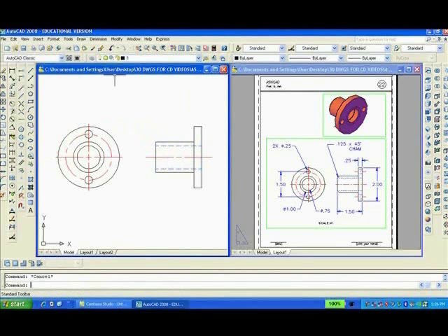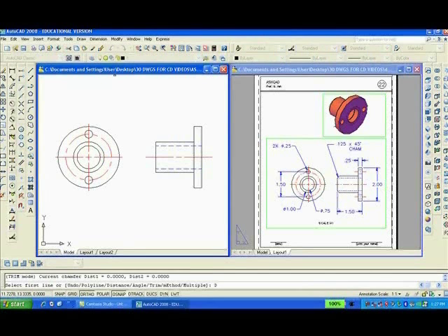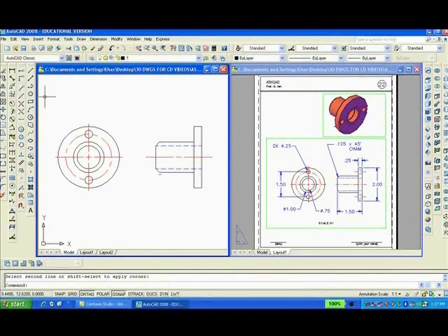So far, so good. Next, you want to type CHA, enter for a chamfer, D for the first distance, 0.125. They ask for a second distance, just hit enter to accept it. And then pick the two lines, here and here, enter. Here and here. And of course, if you're looking at this from the outside, which we are, we should have a line from here to here. You would see that edge.